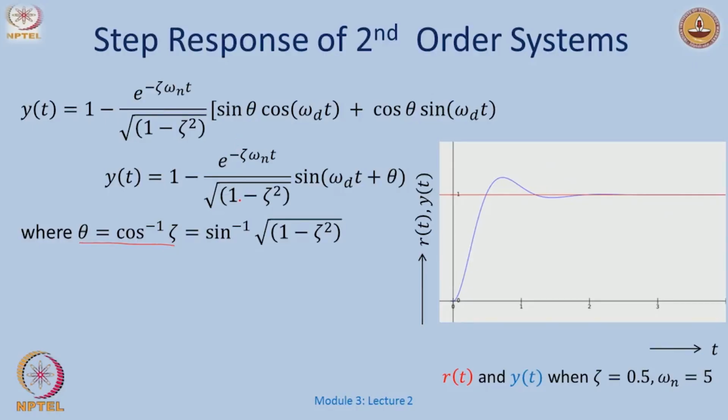Okay. So how does the response look? Y of t goes, so I want to track this number 1 and I go up and overshoot, and then I go below 1, and then I eventually go to this number. Which I can directly say here now, I do not really need to compute the steady state error. Just by looking at this, I can say that the steady state error at infinity is just 0. We will do more analysis on this, but just as a passing observation, I am just introducing you to these terms at the moment, right.